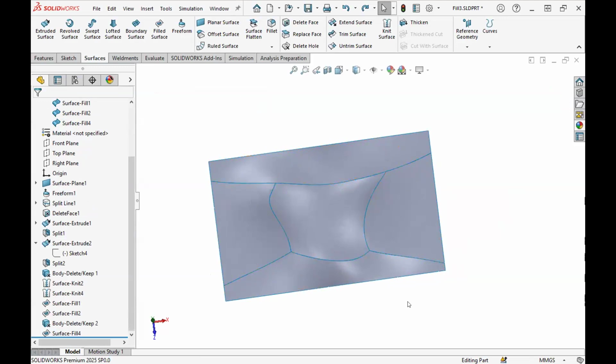But depending on the state you're receiving your model in, maybe it's already had a hole punch in it, you may need to keep an eye out for issues like this where the edge is too long for the opening, or if they're too short. If they're too short, I would rather just try to select another edge in there rather than jumping the gap using fix-it boundary. So it can technically do it. It's not going to work as often as it does for trimming back.